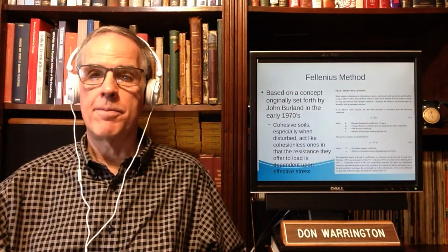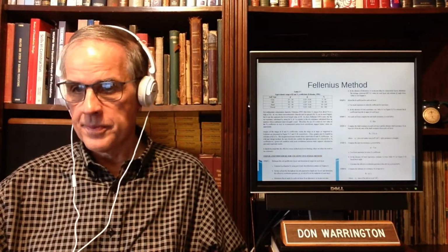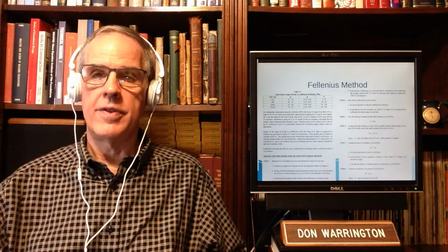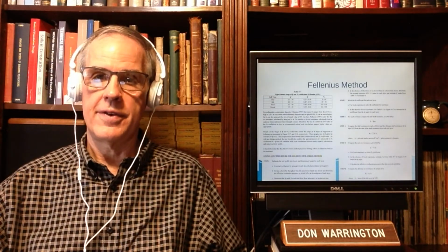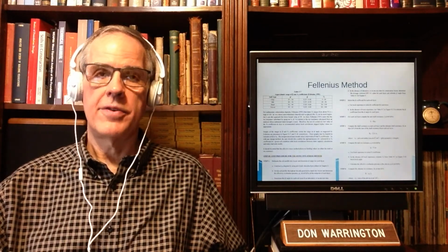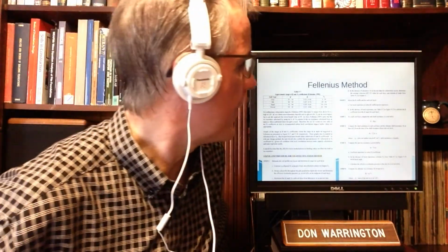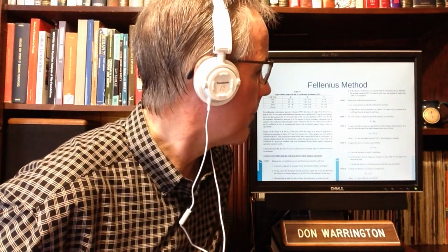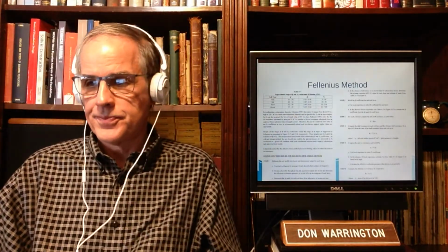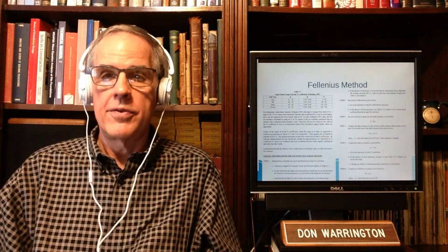And that's basically Bengt Fellenius' idea behind his method. All of the little fs's and the qt's at the toe are based upon, in this case, fs equal to beta times p naught, or the effective stress.